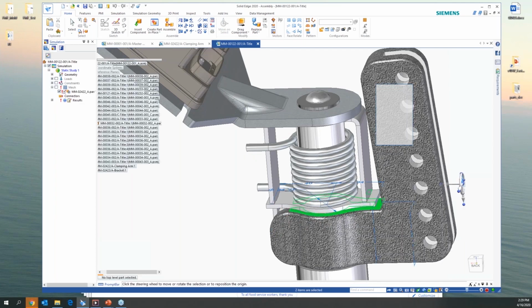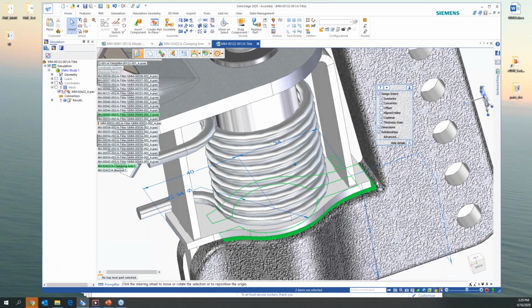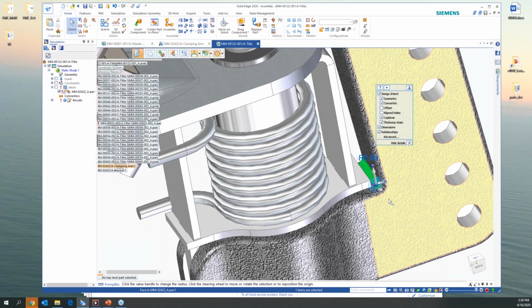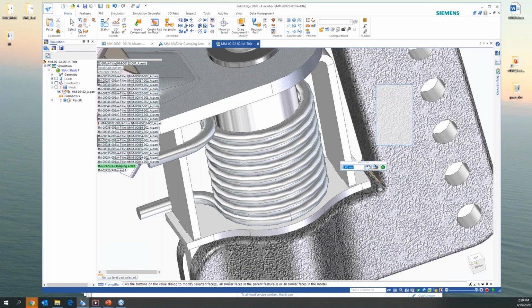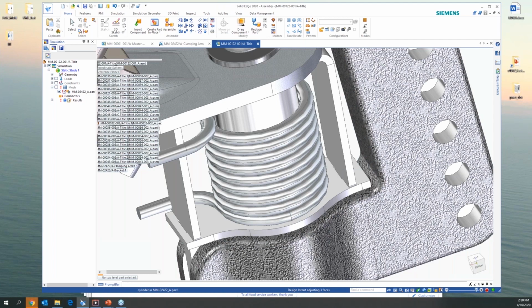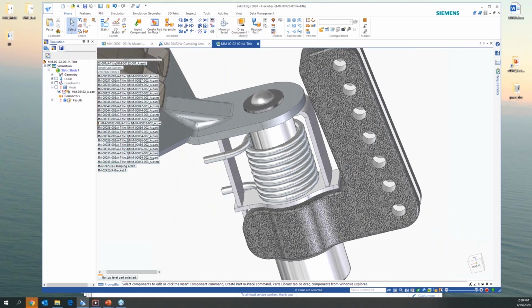which is a really strong tool for Solid Edge. Okay, so that looks good. But also, remember in this area, I've got a 2 millimeter radius in this corner. I want to make that radius there, and let's just make that 5. But I don't want to go along my whole chain radius. I just want to make that individual radius. So I just want to make sure I'm picking the individual radius. Let's change that to 5. All right, that looks good. I can exit out of there.